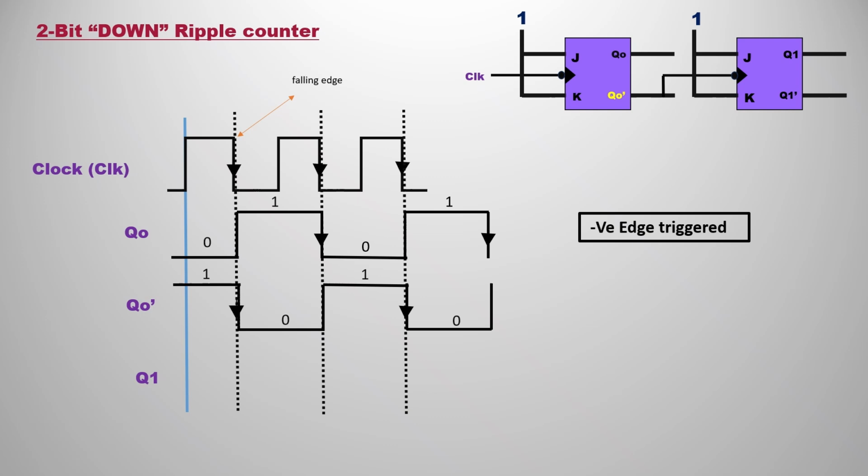As a flip-flop responds to the clock, if you observe the second flip-flop, the clock is Q0 bar, not Q0. But we have already obtained Q0 previously, so we just flip that Q0 and obtain Q0 bar. You can see that, just a flip. Now we can apply the negative edge triggering for Q0 bar, and we can simply formulate Q1, because each negative edge will trigger Q1. Now we obtain Q1. At the first falling edge, I have raised it. At the next falling edge, I have brought it down. Like that, even if you have a bigger chain or longer pulse, you can do that, because if you compare with the truth table, it also works.